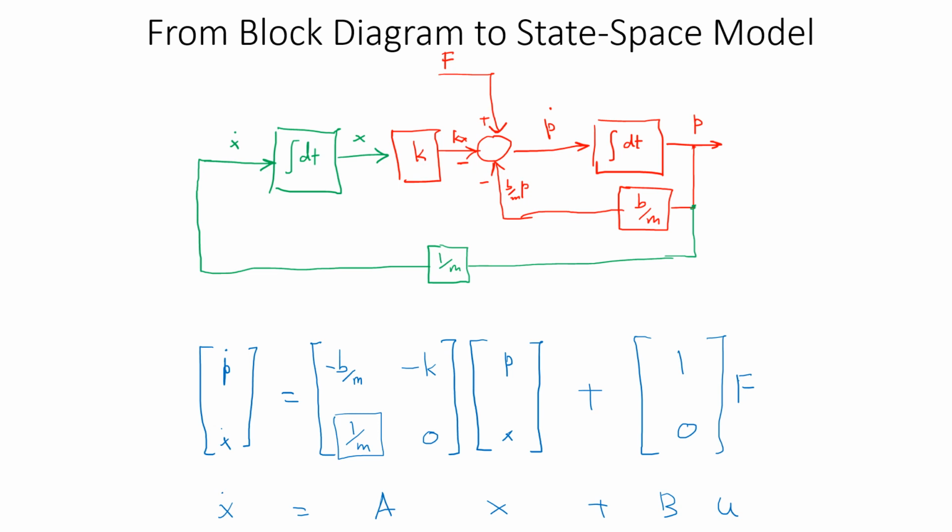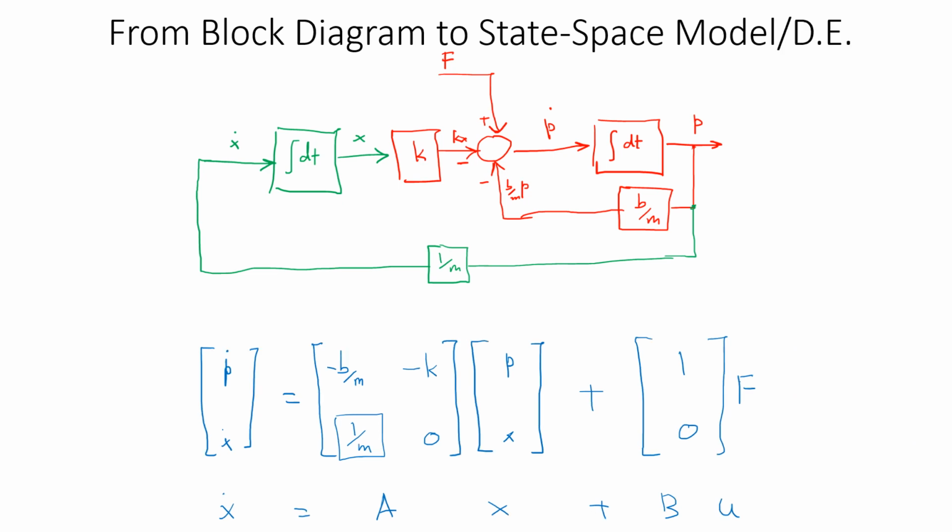And if you in that particular sense require, for example, a specific output equation to be written down, you can obviously write that one down using this simple notation. In this case, D is 0, so that is well understood, but you can obviously select any of these states to be declared as the output. So you can obviously do that as well. And if you need to further convert it into a differential equation, all you need to do is to take this form in and use the Cramer's rule that we have already studied to construct that.